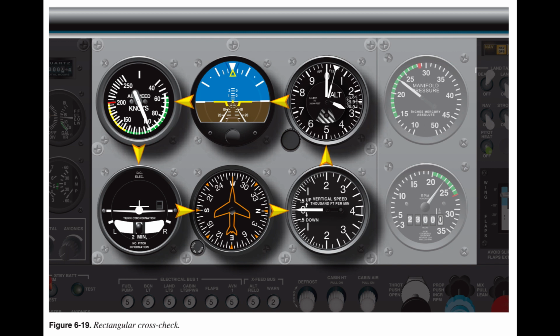It may be caused by failure to anticipate significant instrument indications following attitude changes. For example, in a rollout from a 180 degrees steep turn, straight and level flight is established with reference only to the attitude indicator, and the pilot neglects to check the heading indicator for constant heading information. Because of precession error, the attitude indicator temporarily shows a slight error, correctable by quick reference to the other flight instruments.